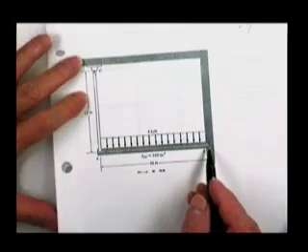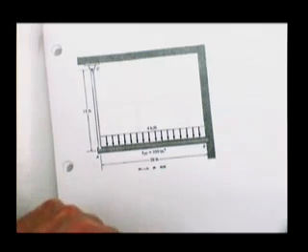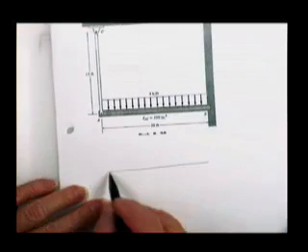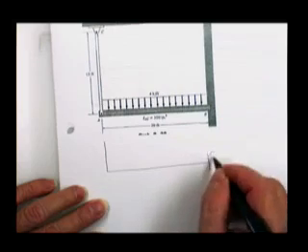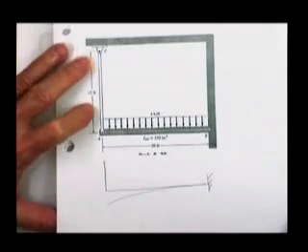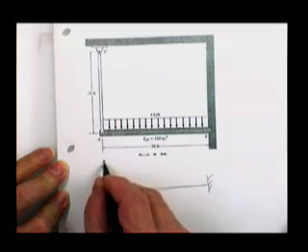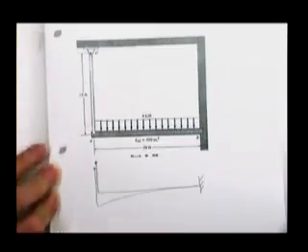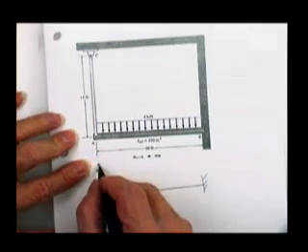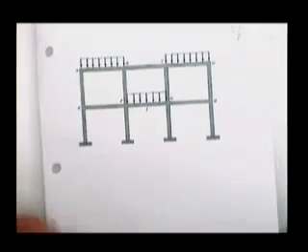Cantilever beam with a rod attached to it. Probably what I would do is I would go ahead and just say it looks like this. Cantilever beam. Let it bend. Admit that the rod is only in tension. And realize that there's an undesired deflection on the end of that stick and make it go away by pulling up on the end of the stick in a secondary solution. All right.